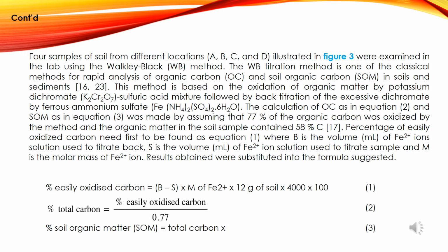The soil taken from the 4 locations from A to D were analysed by using the Walkley-Black (WB) titration method, where the oxidation of organic matter by potassium dichromate sulfuric acid mixture, followed by back titration of the excessive dichromate by ferrous ammonium sulfate, were monitored.